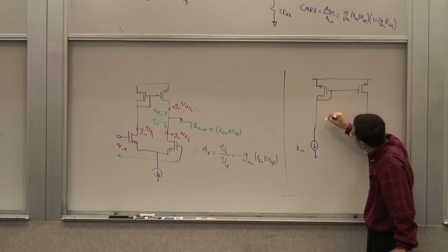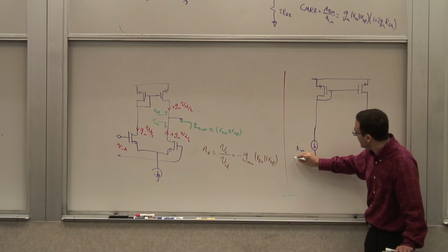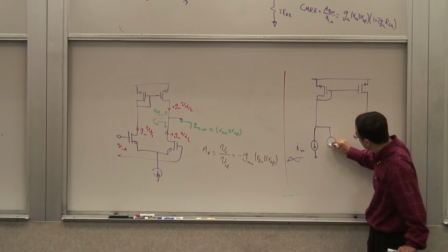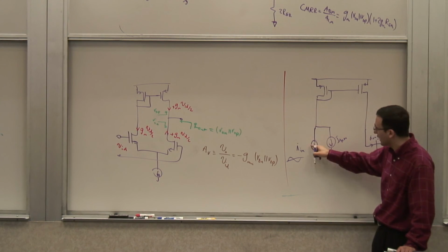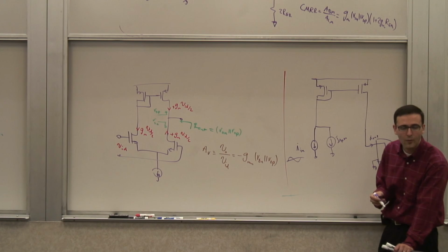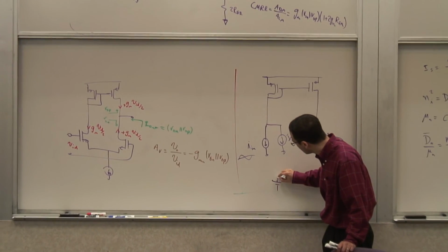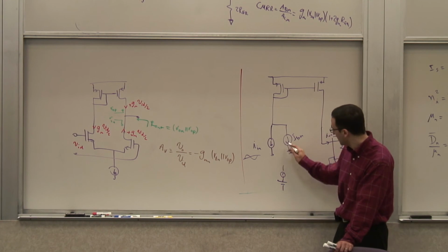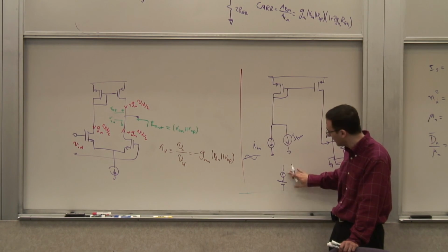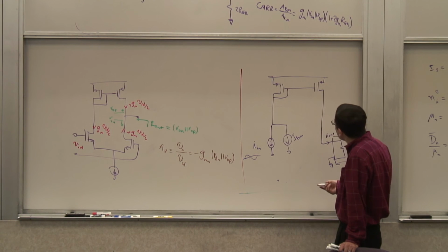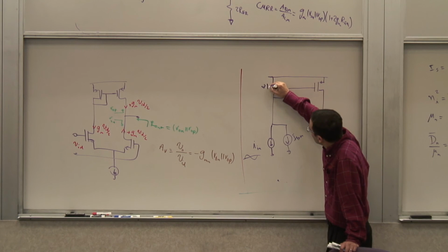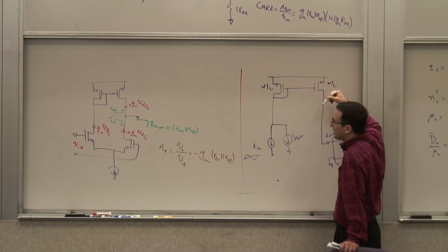Now, I also need to make, see, this may go negative. If it's just a pure AC thing, this may be positive and negative. So I need to maintain a constant bias current. So I can have an I bias, which is constant. And on top of that, I have this AC signal applied. The same way that if I wanted to apply an AC voltage, I put it on top of a DC level for biasing. But for current sources to add them, you have to put them in parallel. So now, is this an amplifier the way it is? No. If these W over L ratios are the same, this just replicates that.